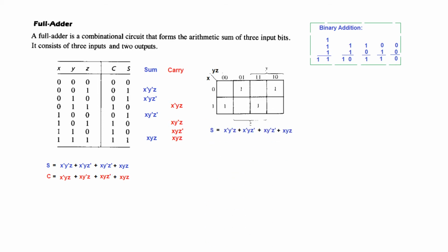And now we'll take help of a K-map to simplify, because this may not be the simplified form. So it is better that we use a K-map. I hope you have learned how to draw a K-map. So we have 3 variables, so we'll write x and y, z, 0, 1, and 0, 0, 0, 1, 1, 1, 1, 0. This is tricky. You have to remember that 0, 0, 0, 1, and then you go to the last one, 1, 0, and then come back for 1, 1.